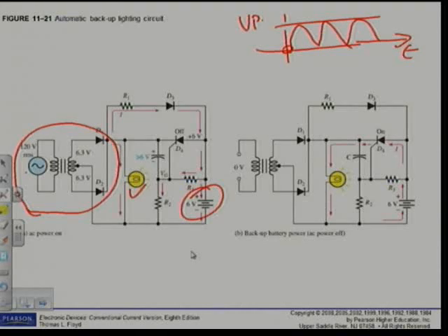And now another story. We are going to have a look at this SCR. What will happen? On this side, we will have plus 6 volts. Here we will have a voltage less than 6 volts. That means that SCR will basically be reverse biased. It won't be able to switch on. All right. That condition will go on.